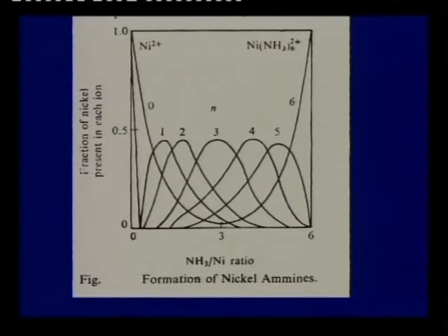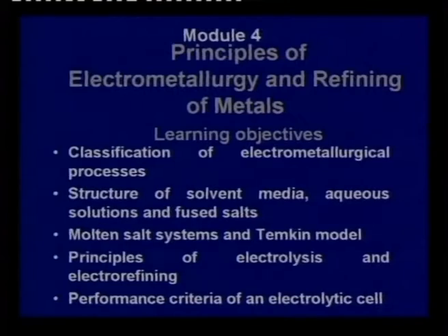An interesting thing I have also said is that while nickel and cobalt can be precipitated from acid solutions with hydrogen gas pressure in the normal range, by adjusting the pH, the particles that come out can be of various shapes depending on some catalysts that we put in the system, and we have talked about some catalysts that give rise to particular shapes of nickel nuclei. For more details, you have to see the book.